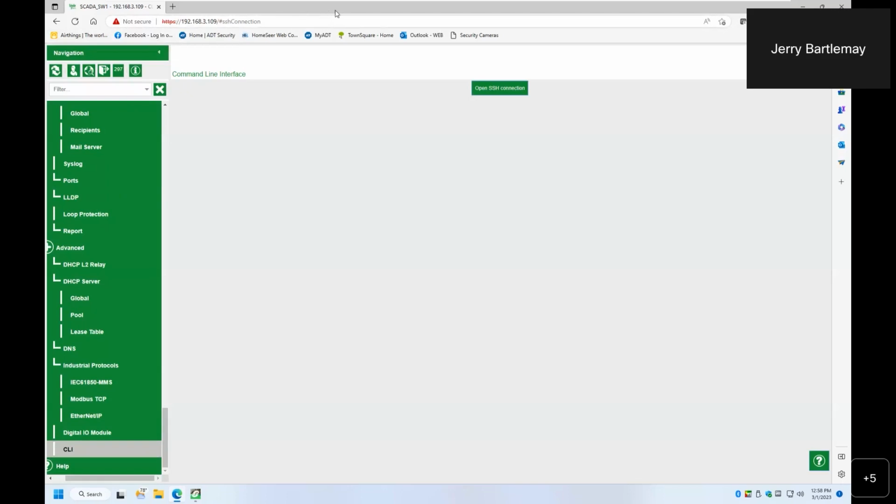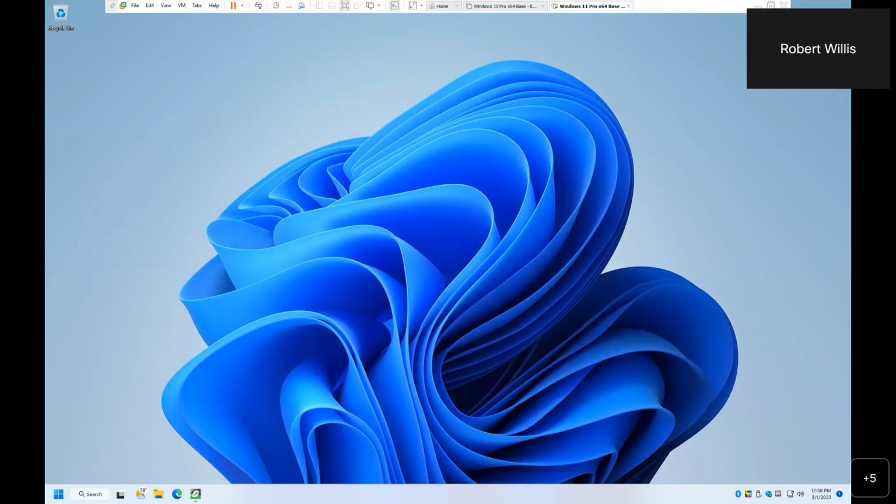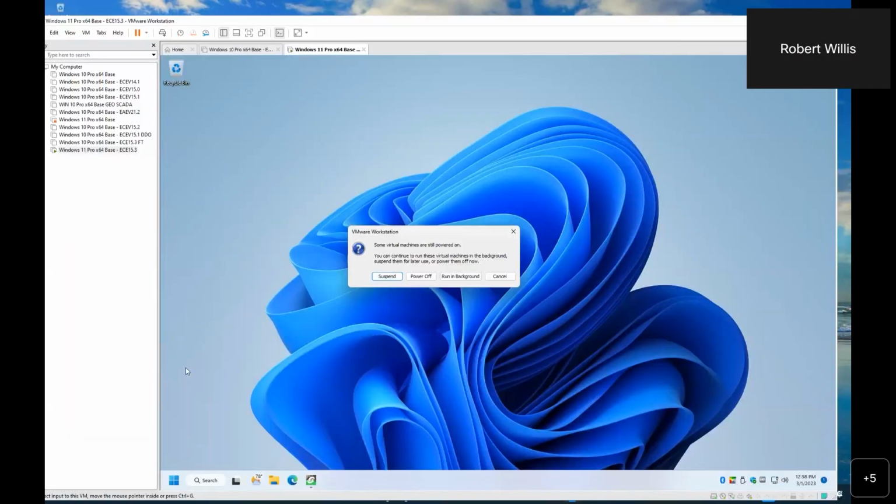There was one question up here about hazardous locations. I know that our managed switches have an ATEX rating. I don't know if they go beyond that. I believe the switches are Class 1, Division 2. That should be listed in the catalog, okay? And so that should be listed there, Class 1, Division 2, both UL and CSA.